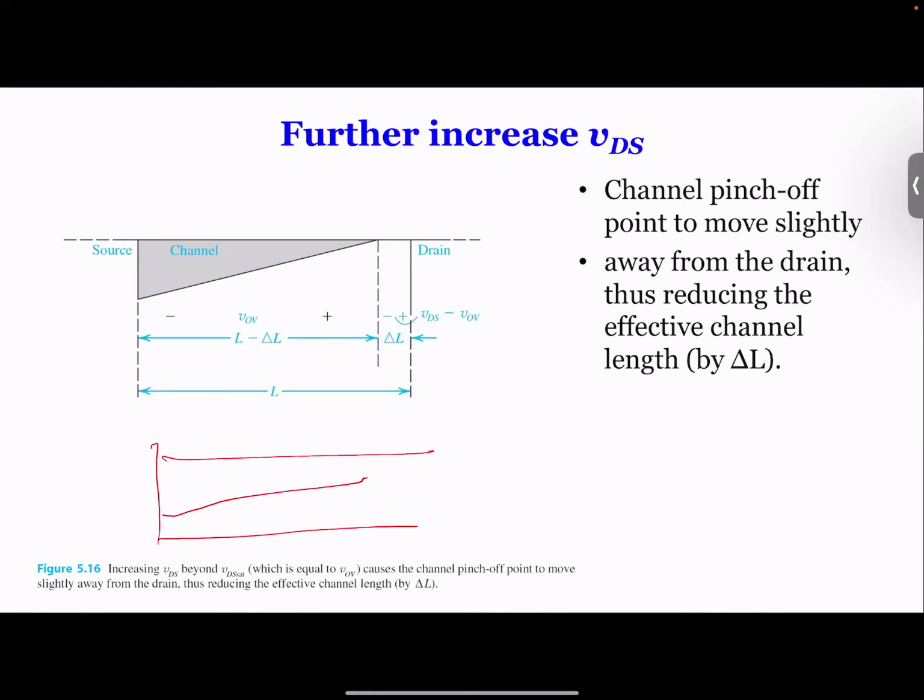We have a channel, like this. Remember what we talked about regarding the channel effect? All the electrons try to flow so that one side is bigger, you get a trapezoid, and the other side is smaller. That's where our equivalent current is actually smaller than when it's wide open. So we took the middle, right? That's how we got the saturation region, and the linear, the triode region. In the saturation region, it's different.